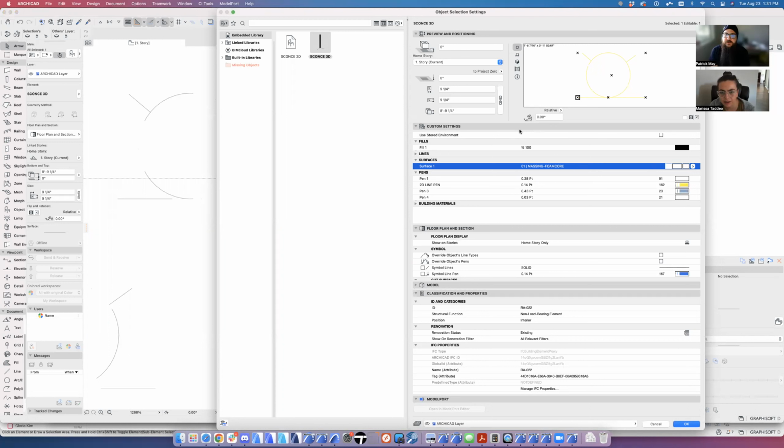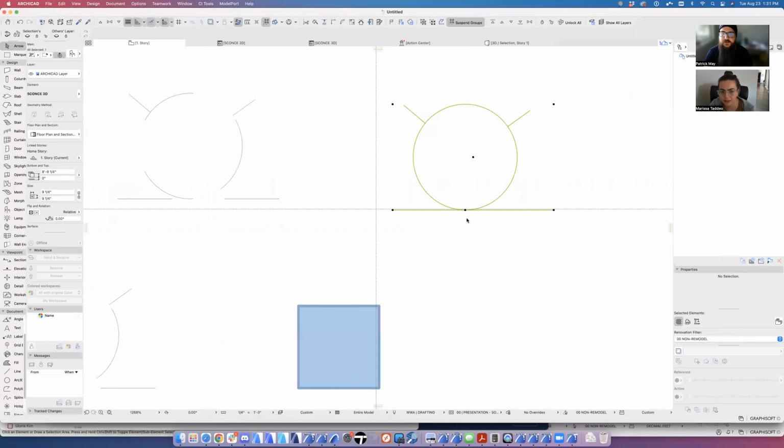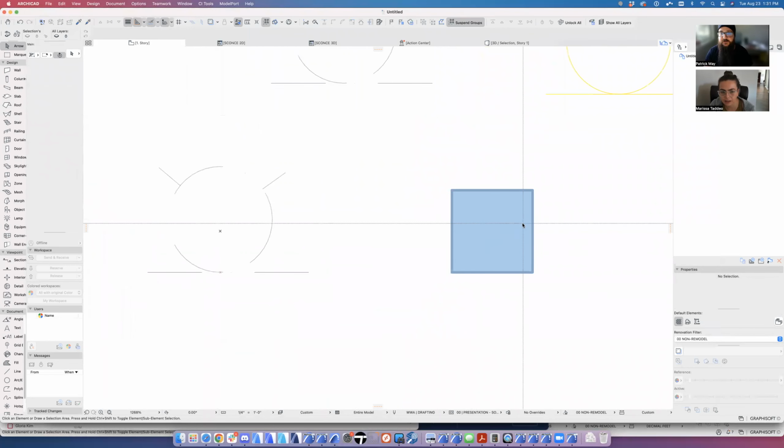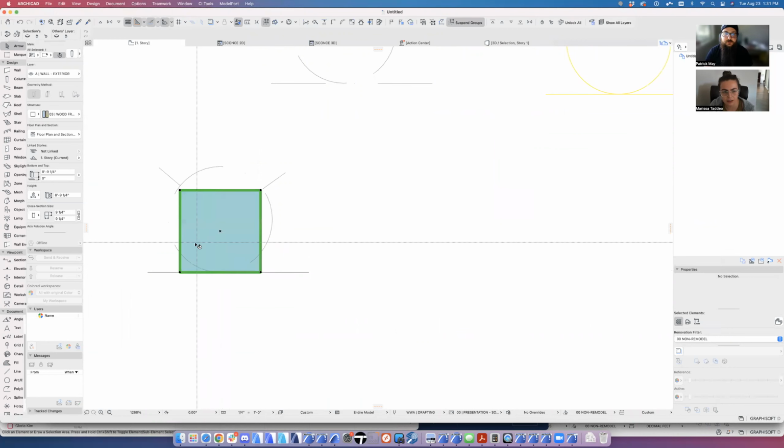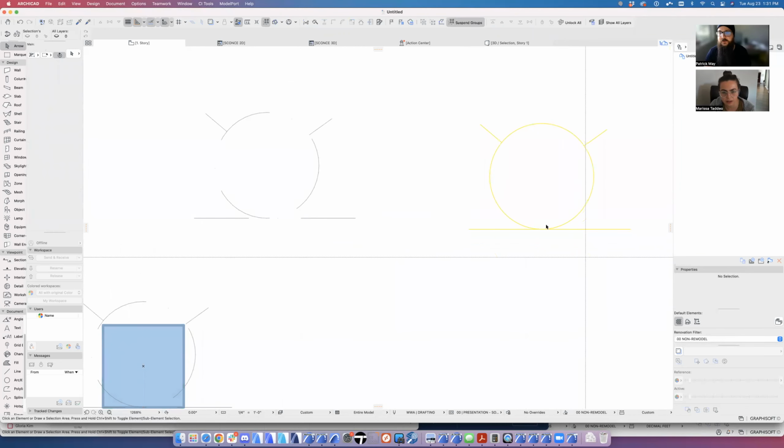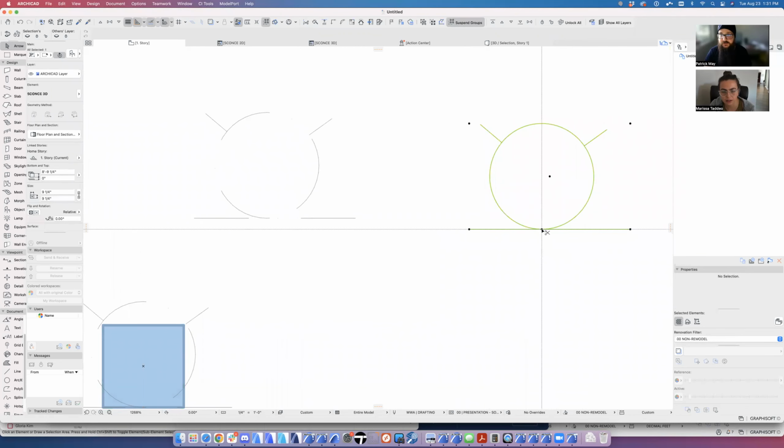I know that that's really kind of daunting to think about, but once you've done it once or twice, it gets to be pretty simple. You're saving out the 2D, you're saving out the 3D. Most importantly, you're saving them out with a relationship to 0, 0, so that the two are relating to each other. And then once you combine them together, we have a hotspot right here, so I could snap that right to the wall. The center hotspot here is a little bit wonky because I wasn't careful about how I drafted it. If the distance from here to here were equal, that would be in the center of the element.